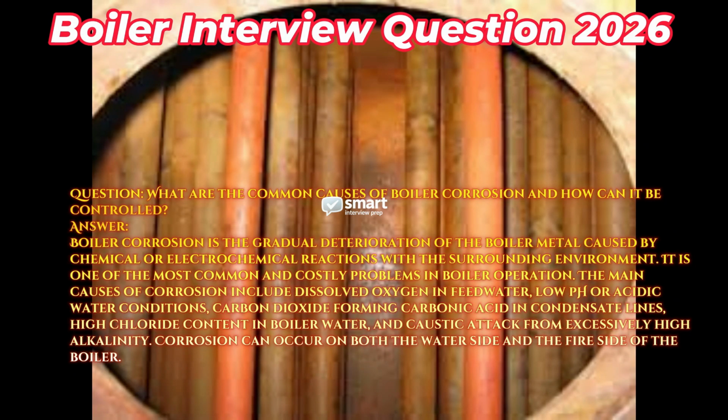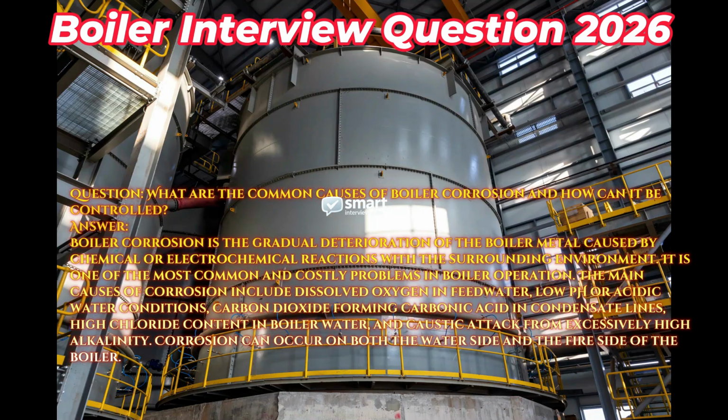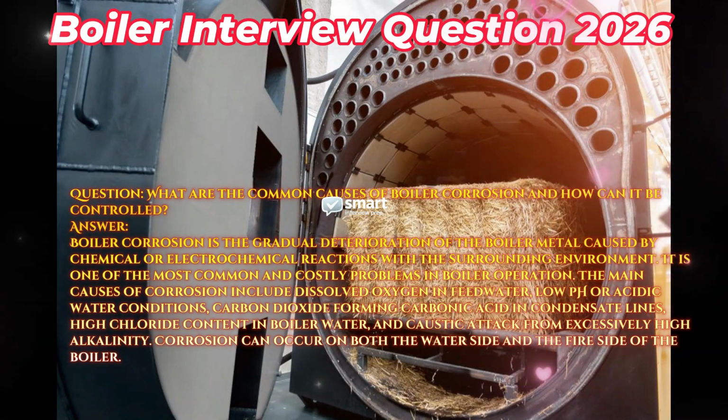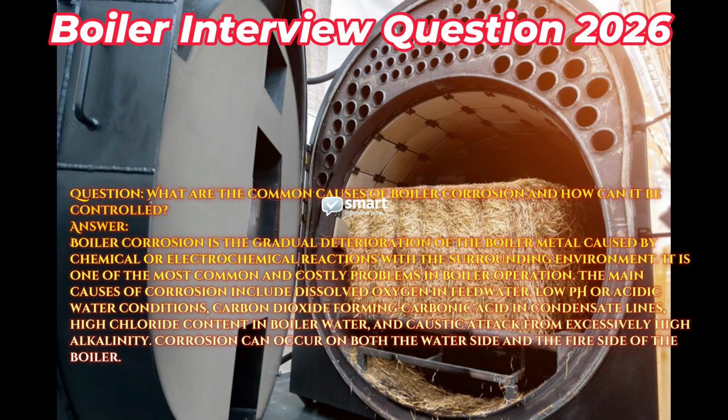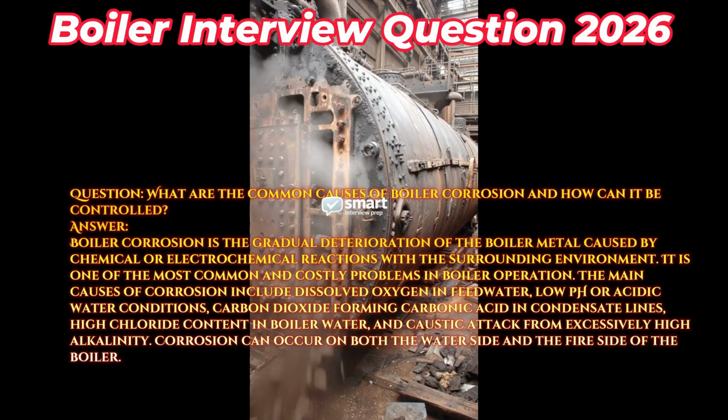The main causes of corrosion include dissolved oxygen in feed water, low pH or acidic water conditions, carbon dioxide forming carbonic acid in condensate lines, high chloride content in boiler water, and caustic attack from excessively high alkalinity. Corrosion can occur on both the water side and the fire side of the boiler.